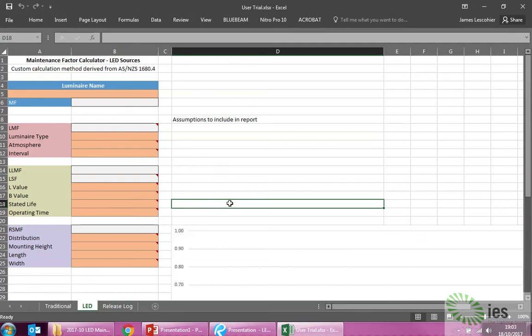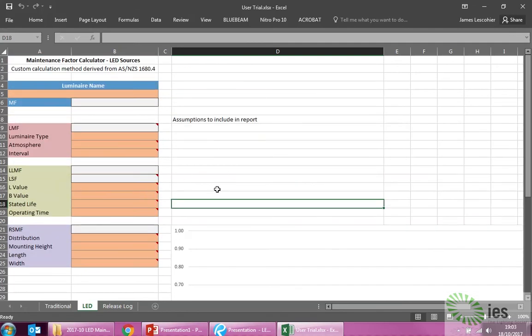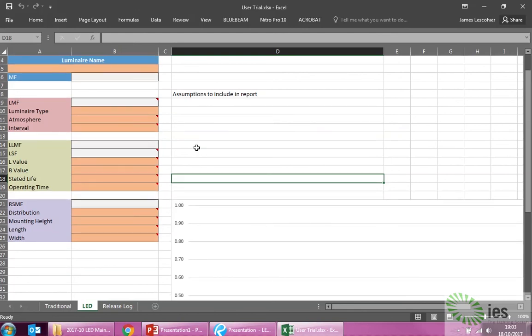And so I've tried to represent that as much as possible on this chart, but you don't see it actually when you plug in that number there. You mostly see it in my chart based on the deaths. I assume that if 50% of the luminaires are below their stated value at L70, they're actually degrading faster than the ones that are only 10%. So I'm treating it as a degradation past its rated life figure, is how you see it on here, as well as it actually does affect the crossing point.